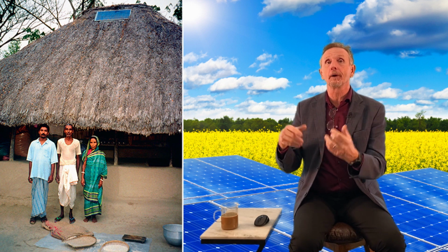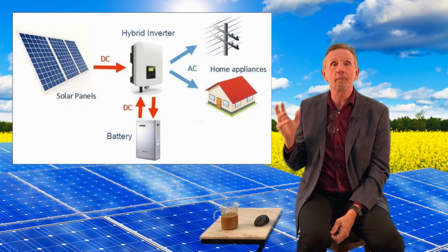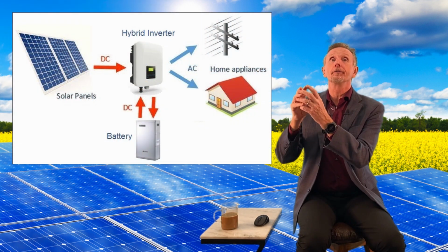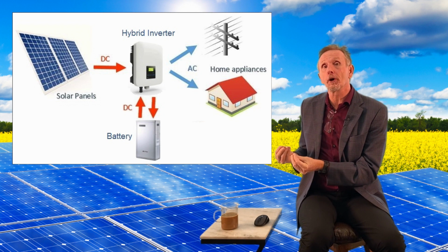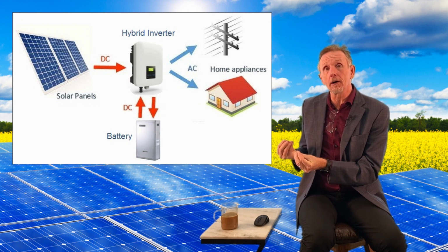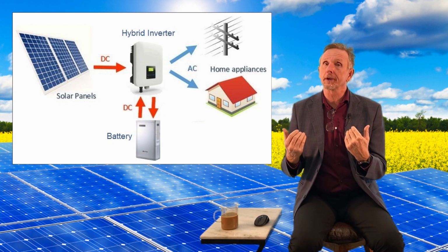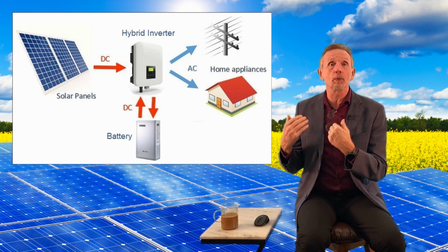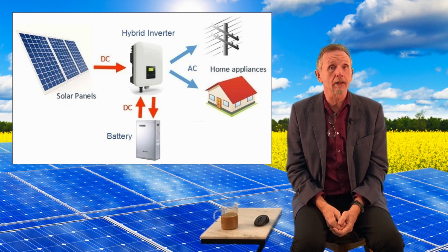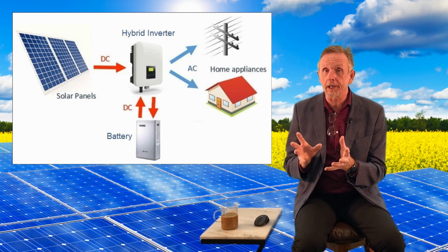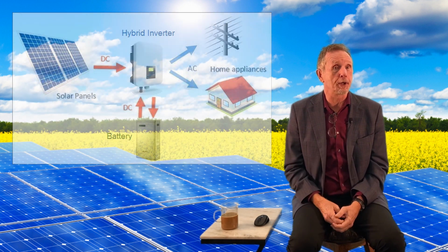The solar panel goes up on a roof, comes down into some LED lights, which are very low energy, and you tie into a battery system in the house. So the solar panel charges the battery all day long, and they're getting electricity during the day. Then in the evening, when the sun goes down, the battery power will power their LED light bulbs and other small electronic devices till it's time to go to bed.